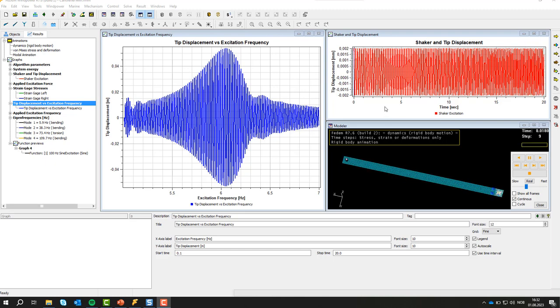First we can have a look at the excitation frequency, the sine sweep between 5 and 7 Hz, which I applied in 20 seconds. And here you see the dynamic response of the excitations on the structure. Although this is only the rigid body part of the displacement, since I haven't performed an inverse CMS transformation of the supernode displacements yet.